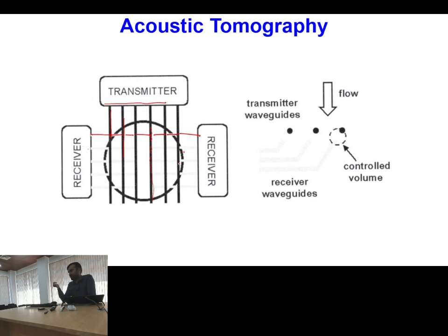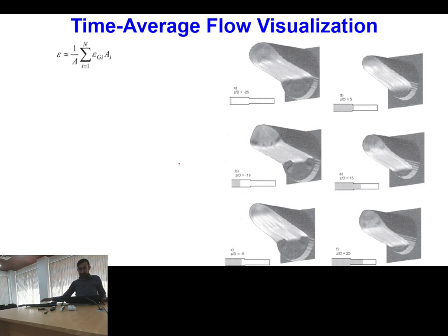so this corresponds to one particular time. Now, if I increase this time period, do the measurements and keep a record for some time interval capital T, and then take the average of the data at all the points over this entire time period T, I can get the value of the time averaged phase distribution function or void fraction.